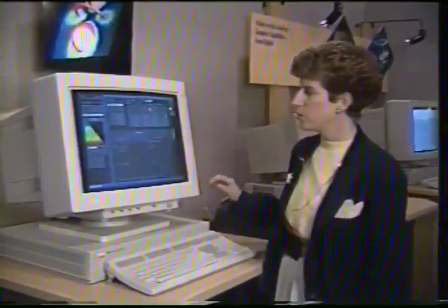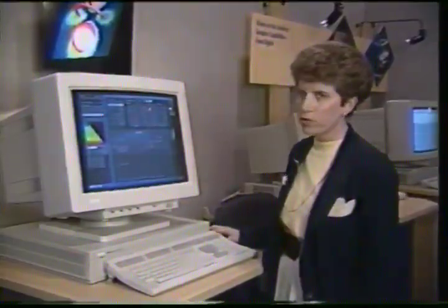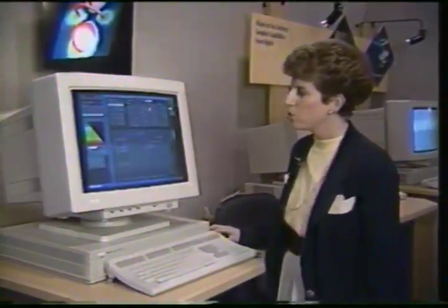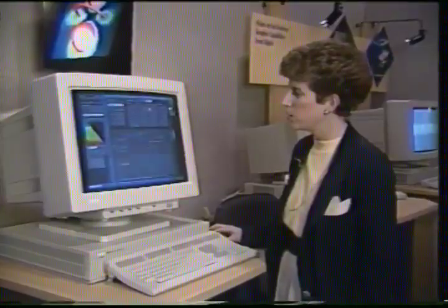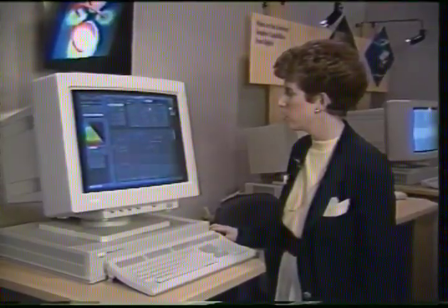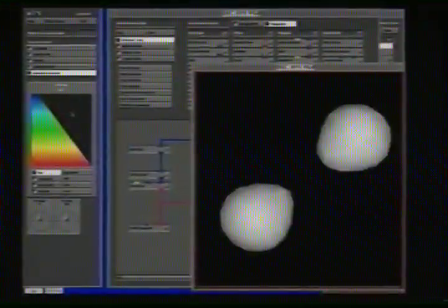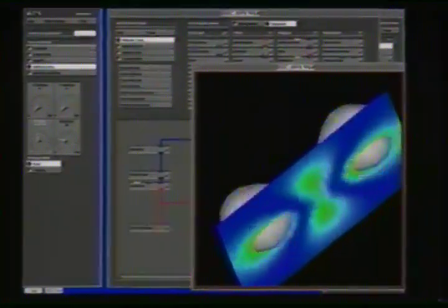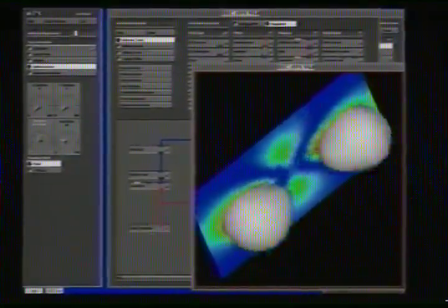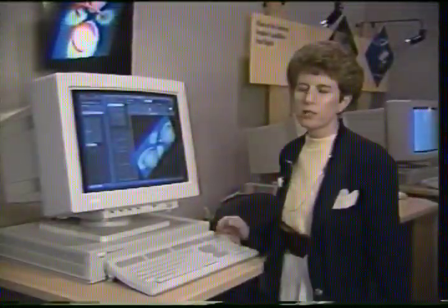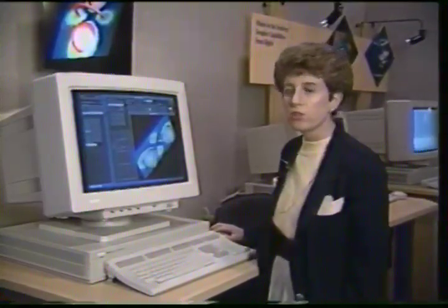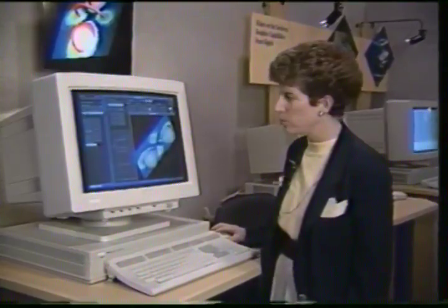We have a data input module that then sends the data down through 2 different paths, one to create that surface that we've already seen and the other to create the arbitrary slicer. Let's bring up the image window again, go to the slicer module, and we can see the slice plane moving dynamically through that module. Now what does a slice plane do? Basically what it does is it colors a 2D slice through the data set based on the value in the data set at that particular location.